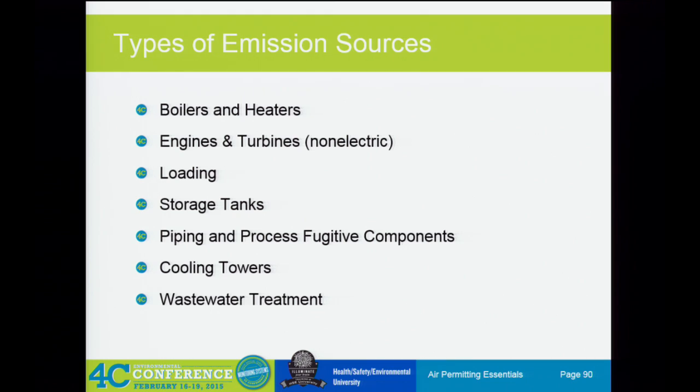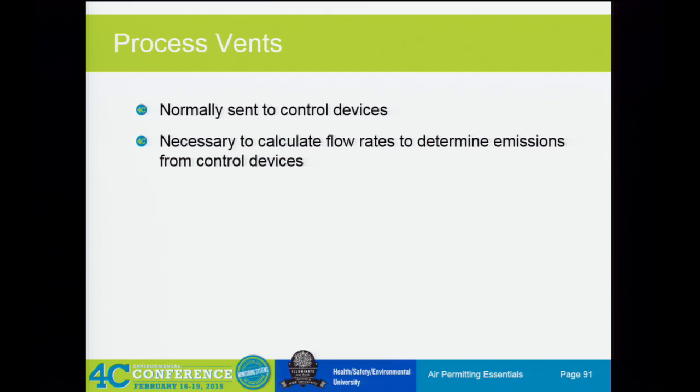Loading is a source of emissions. We'll talk about how you calculate loading emissions. Tanks are a large source of emissions. Each tank is its own source. Piping and fugitive components, that's what we call LDAR. Cooling towers are a source of both VOC and particulate. And then the wastewater treatment plant. Like I said, process vents are normally sent to control depending on their size.